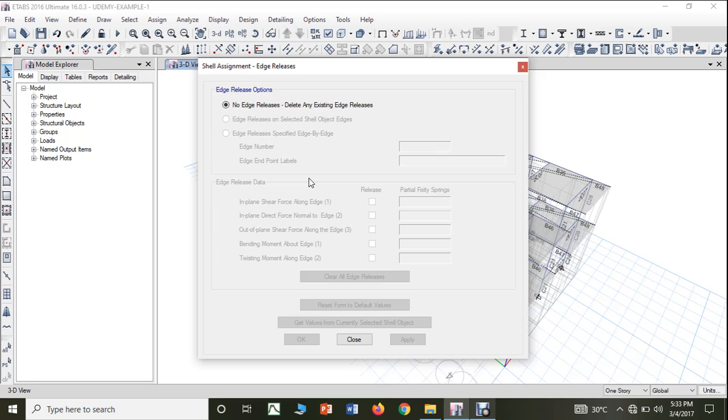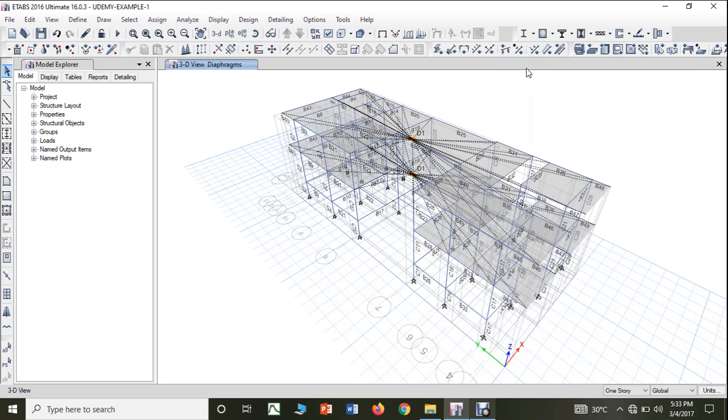In the same manner, here you can do it. For example, if you want to define one particular slab as per that, you can choose which joint, which number is to be released, that is the shell adjustment, which edge you want to release. That means if you release it, it will be taken as continuous. If you restrain it, it will be considered that the edge is discontinuous.